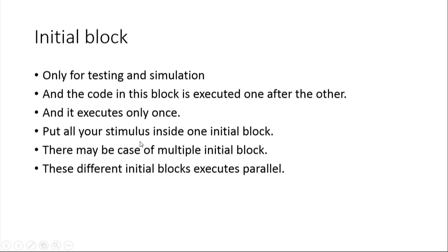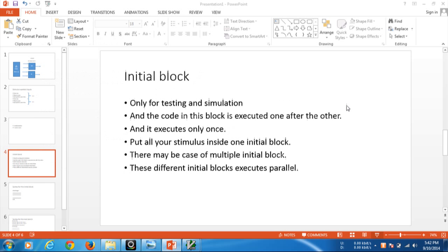The most important thing is that the code in the block executes one after the other, but when you compile it, it appears that all the code is executed at the 0th time, all at once, not step by step, as the processor speed is very fast. This is what we discussed in the initial block.